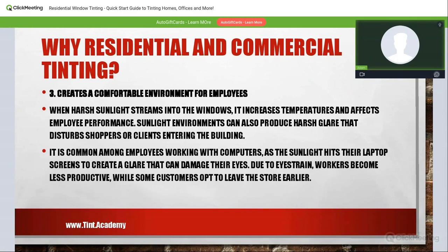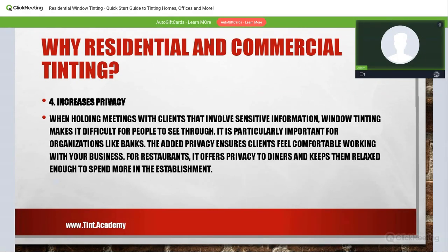Typically, in my business, I use a mirror film that has a 15% VLT, just like car windows. So 15% of the sunlight comes through, which still gives natural light without all that UV. The odd customer wants it blacked out, which we do with a 5% VLT. Just like limo tint, which is 5%, we go to 5% residential film. It's a mirror component that offers reflectivity, which we'll talk about in a little bit, with 5% visual light transmission.